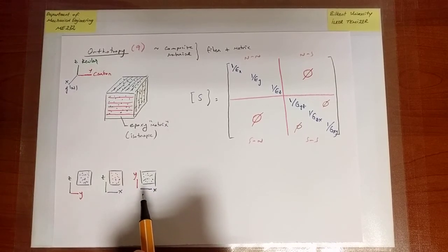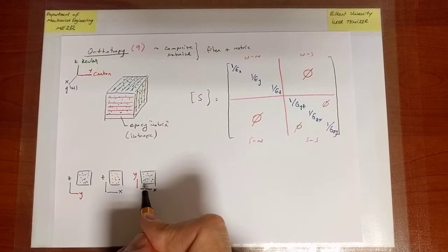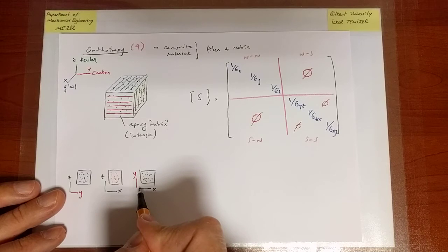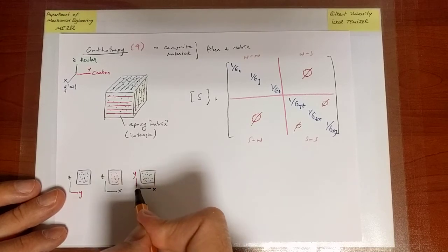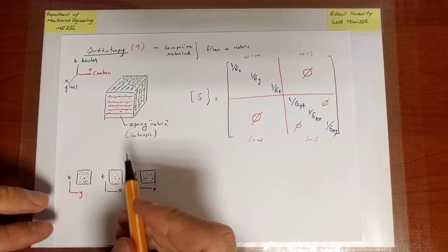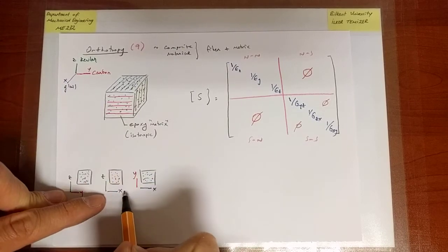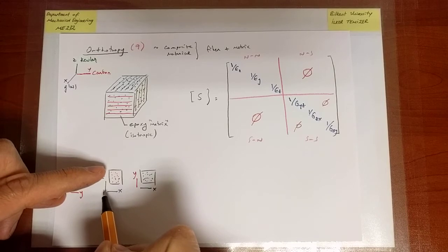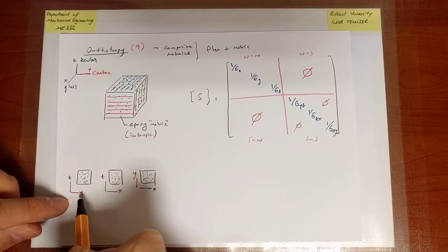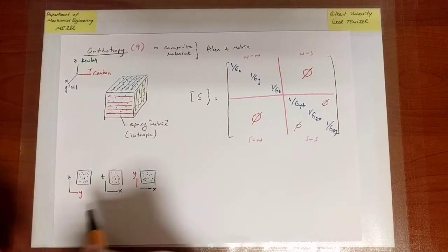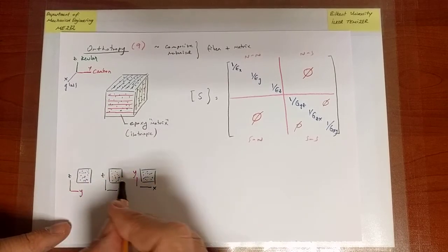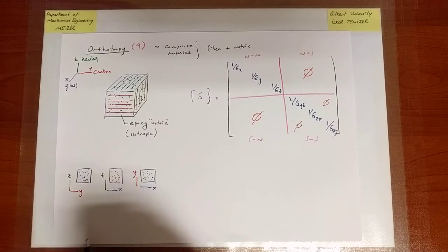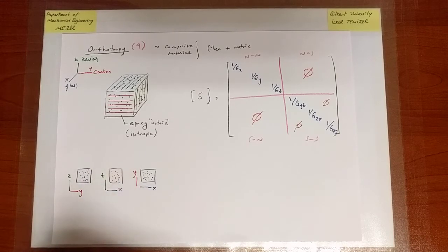So in other words, for instance, the amount of strain you measure along the Y direction when you pull along the X direction. You pull along blue, which is glass, and contraction has to do with carbon. Or you pull along blue, contraction has to do with Kevlar. Or you pull along carbon, contraction has to do with Kevlar. All of these are different, essentially, combinations of materials, and therefore you expect the Poisson ratio associated with them also to be different.